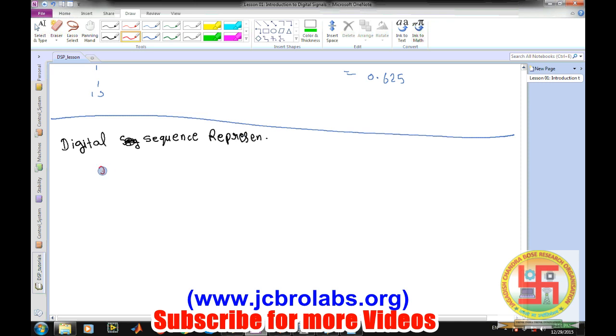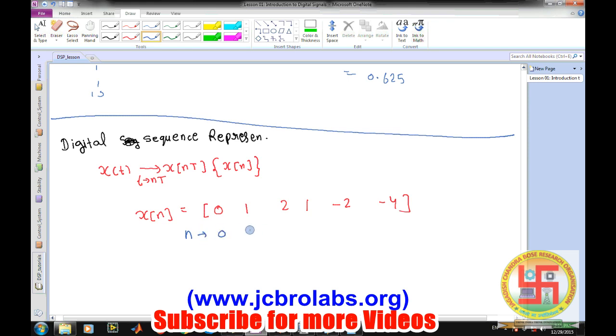It is represented generally, so x of t was the analog domain and we converted it by replacing t by nT. So generally we use x of nT, or more popularly x of n while specifying the numbers. Any x of n, that is a digital sequence, is stored like 0, 1, 2, 1, minus 3, minus 2, minus 4, and so on. If nothing is given, it is by default the index number n, which goes 0, 1, 2, 3, 4, 5.